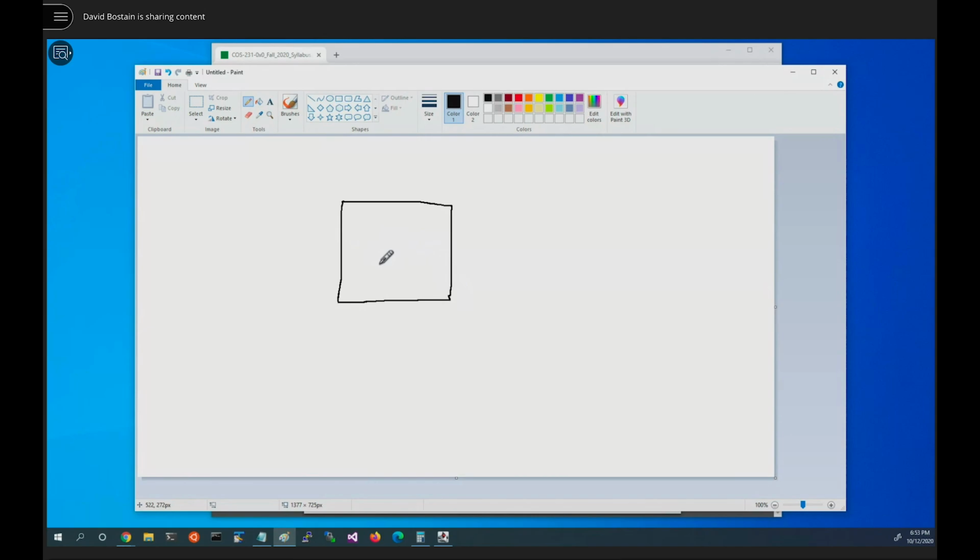But the box generally has the following features. Its outputs will appear on the right-hand side. If there's a Q, it's normally at the top. If there's a not Q, it's normally at the bottom. You might have one of them missing. You might have both. But that's where they'll normally live. Now, everything I draw can be flipped 180 degrees in some pictures depending on what they're doing. For example, if we're building a counter that has to pass the bits to the left, normally we'll flip it over rather than leave it exactly as I'm drawing it here.